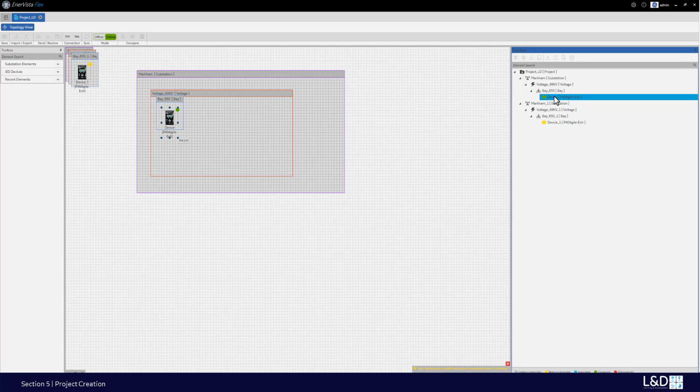So that's something you can do under the project and associate this offline setting file. Use the associate button to make this into the online control mode. So I'm going to switch back to offline again. So that's the demo of how we create a project, how to back up a project, import the project, and how we can associate an offline setting file with a physical relay.